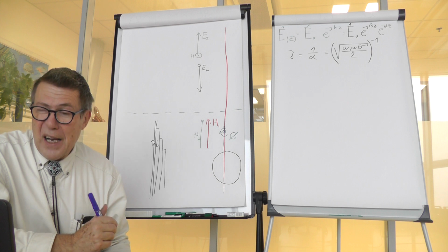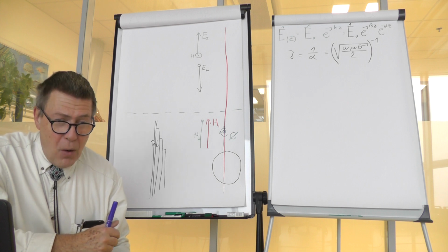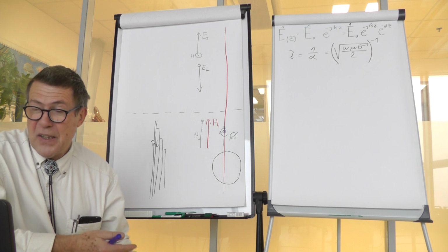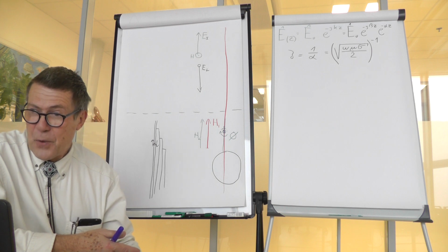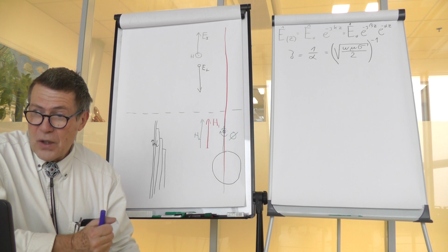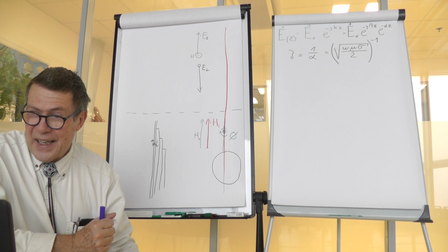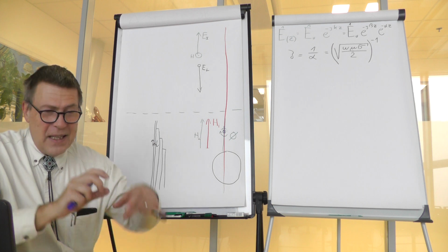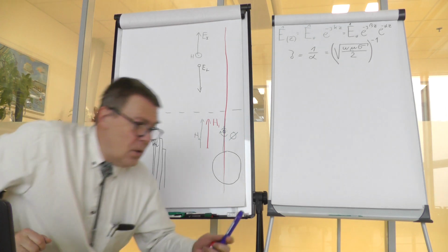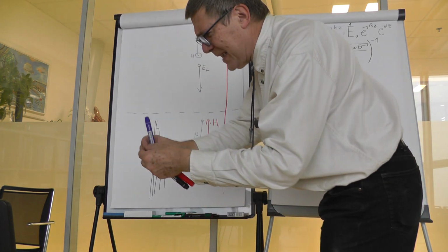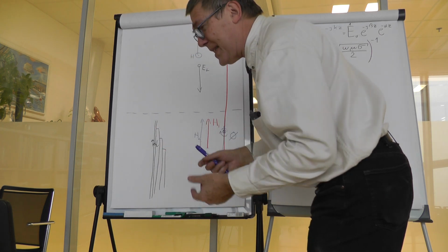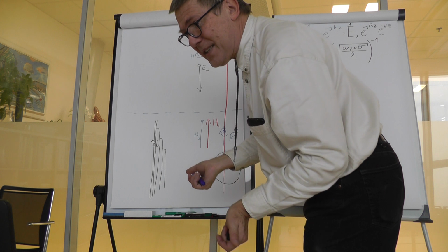The same problem comes for high power devices at 50 Hertz. By high power, I mean generators in the power plant, for example. There you have kiloamperes, and in order to get them through a winding, again there is something like a number of twisted wires, and now this is very costly. You can easily twist wires that are 1/10 of a millimeter in diameter. You cannot easily twist wires that are 2 centimeters in diameter.